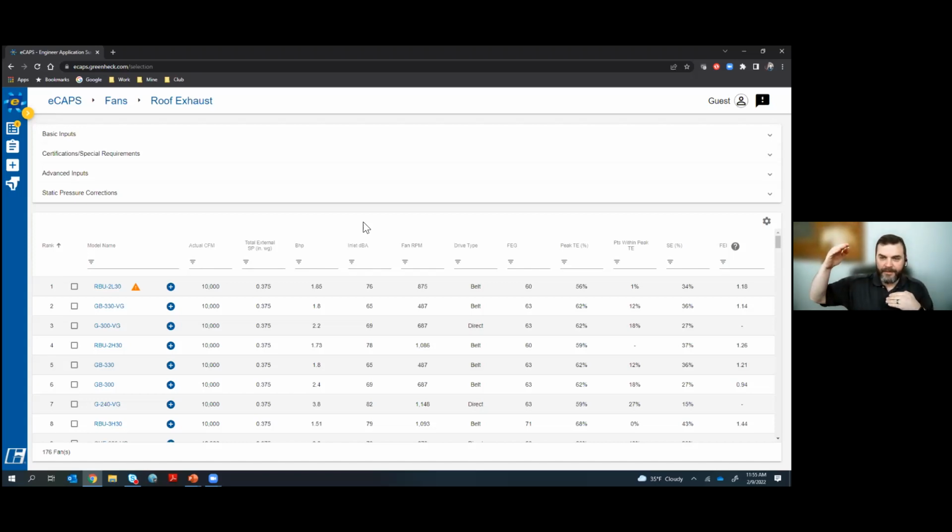I'm looking at those different operating points. I'll look at the 60 hertz operation, max speed. And then, for me personally, I'm a bit conservative. I use 15 hertz as my minimum. I'll try to select the fan size that squeezes in my top end and still brings down my bottom end. Every now and again, you need to dip into that 13 hertz, and that's all right too.